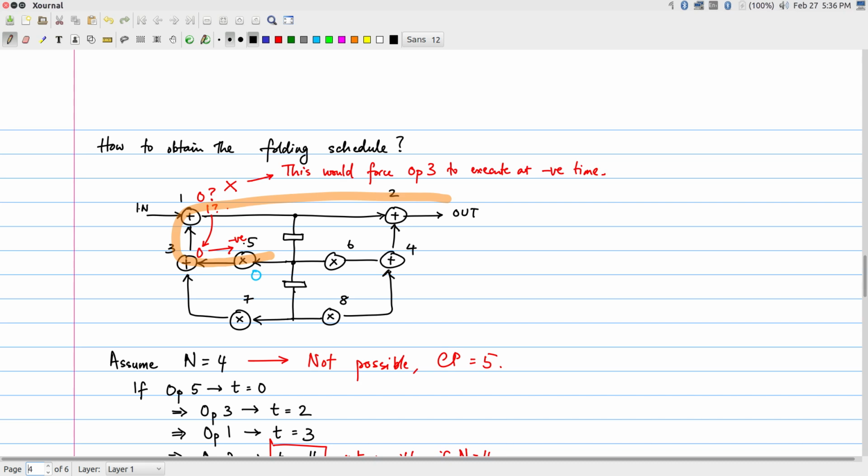My iteration period bound and the fact that I cannot have combinational loops, etc. All of those things intuitively, I know why any loop or a cycle in this structure, the graph that I have, must have at least one delay element on it. So if I delete all edges that have delay elements on them, the resulting graph will not have any cycles. It becomes something called a directed acyclic graph.